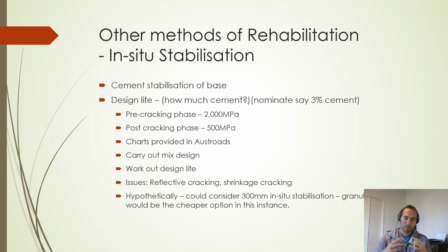In this case, we talk about importing about 100-150 mil of crushed rock, mixing that, the imported crushed rock, and the existing base together to form a 300 mil in situ stabilized base sitting on that upper and lower sub base. And then you have this 300 mil layer sitting on a 250 mil layer, and then you can surface with a spray seal or another 30 to 40 mil asphalt. We've done an analysis and that works in Circly. That's recommended in the report.